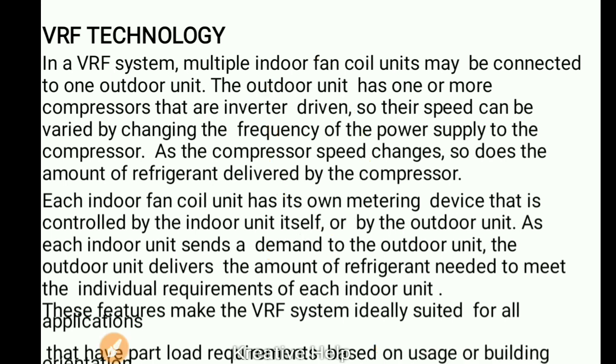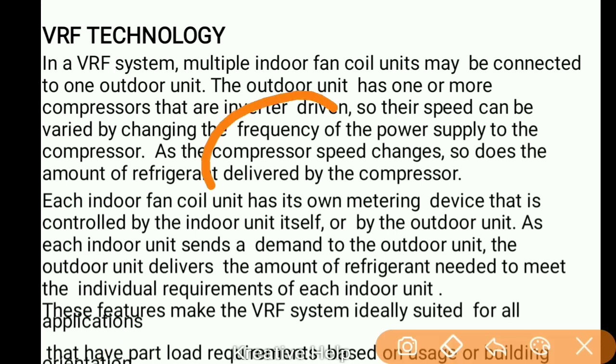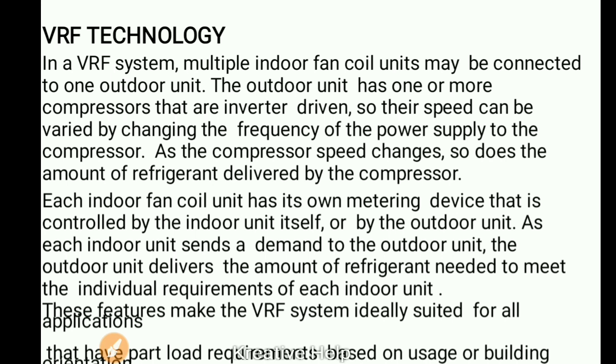We know that most VRV systems are inverter driven. I have explained all these things in the basics of HVAC, so you can watch them from the basic list. Their speed can be varied by the frequency. I have explained how frequency, poles, power, and cos phi are related, and all the formulas are in the basics of HVAC. Changing the frequency of the power supply of the compressor changes the compressor speed, and so the amount of refrigerant delivered by the compressor changes.